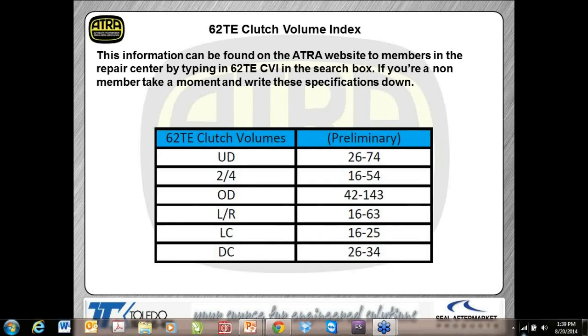As you check out the torque converter here, it looks kind of funny, the 62TE has a much smaller converter. It's called the squish design. They're trying to make these transmissions fit in smaller vehicles, less weight, save fuel. So now we have this converter that actually looks squished, and in this diagram, you'll see exactly what I'm talking about. On the earlier, or on the 41TEs rather, the converter is perfectly round.